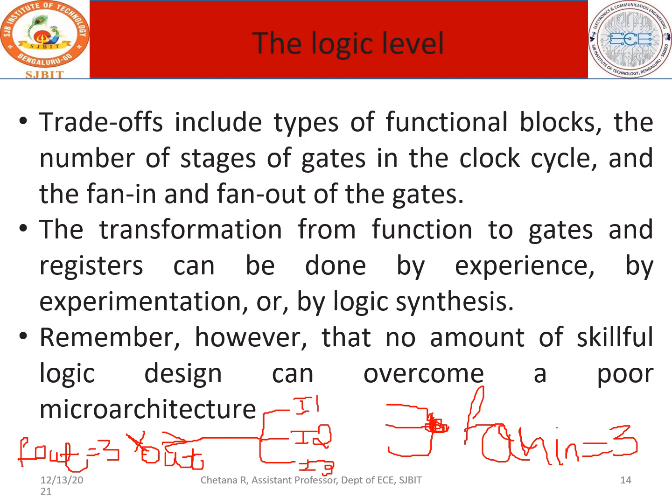The number of fan ins should also be recorded. A gate will definitely support any number of inputs, but the speed is going to fall. Therefore, appropriate inputs should be supported. Most logic families support a maximum of 4 inputs, and there also there is a delay. Therefore, whenever we give examples, they are normally considered with 3 inputs.